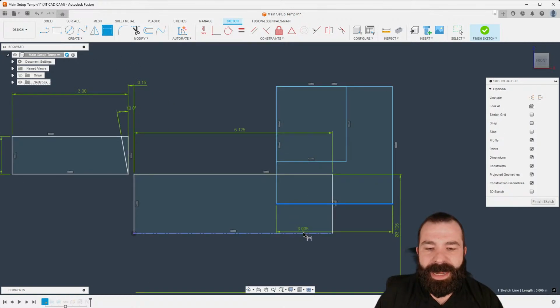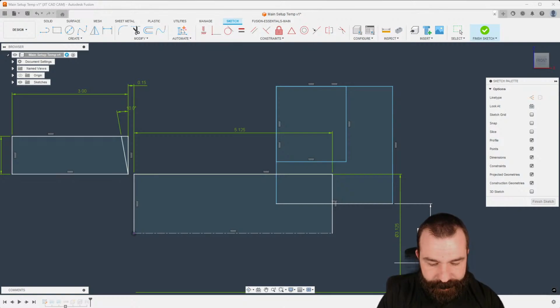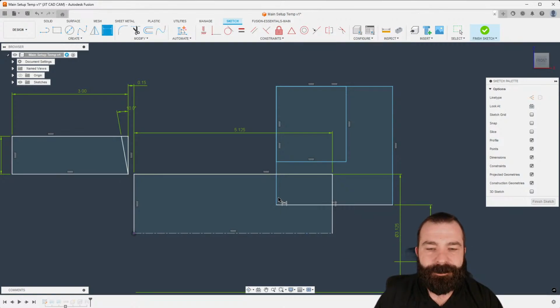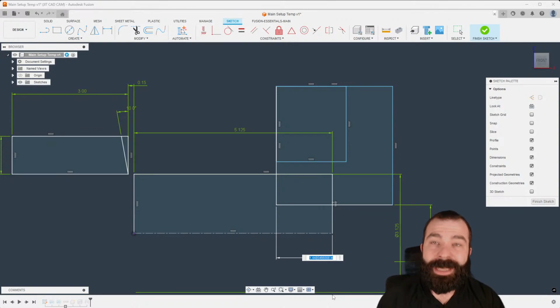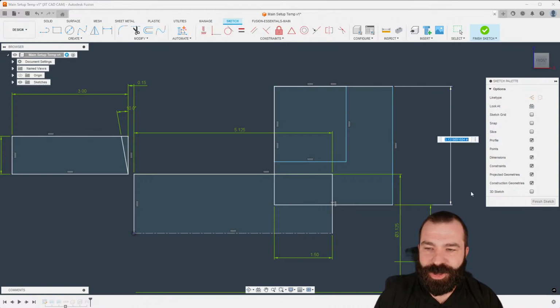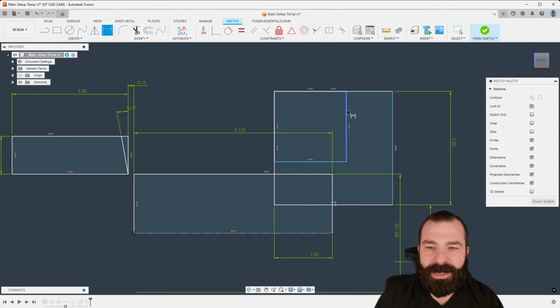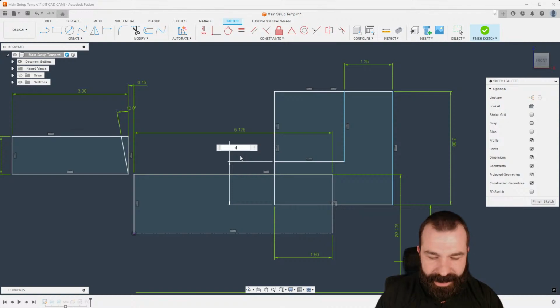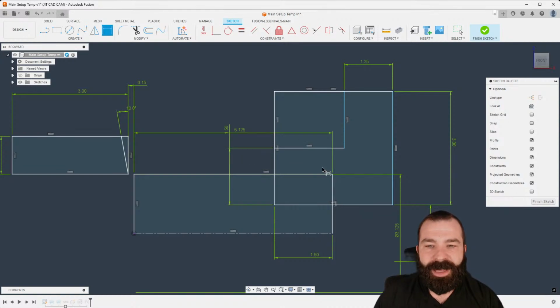So the diameter at which I want to grab onto. So let's set that to 1.5 to start. How far in from the stock front do I want to grab? Now, this is an important one, and I'll show you guys why here in a couple of minutes. And then, of course, how big are those jaws? Whatever your settings are going to be. What is the actual thickness here? Maybe this is 1.25. You've made these yourself or you ordered them online, right? So again, let's go ahead and say this is 5 here.